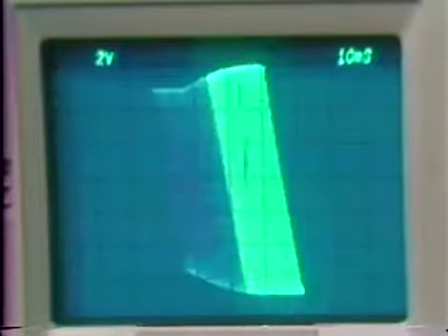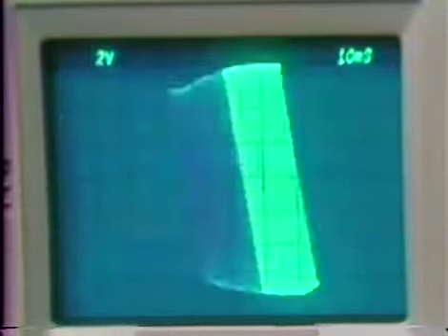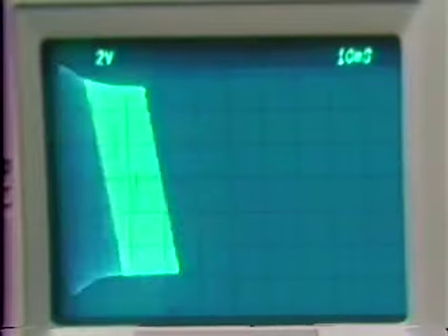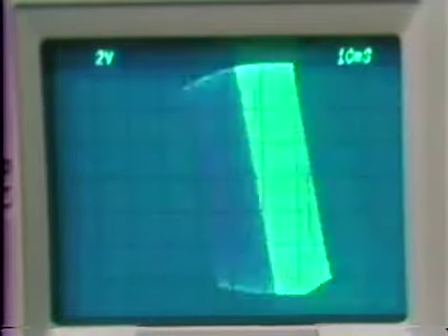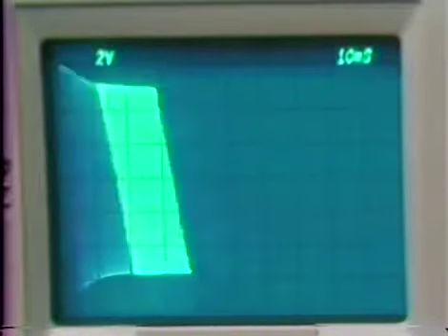Since we have a system with high phase margin, we designed for 75 degrees of phase margin, we get responses that look very much first order. If we had 90 degrees of phase margin, we'd anticipate responses that are indistinguishable from first order responses. This looks very much like a first order exponential. And the time constant of the change in envelope is on the order of 10 milliseconds, 1/100th of the 1 over RC that we shot for.